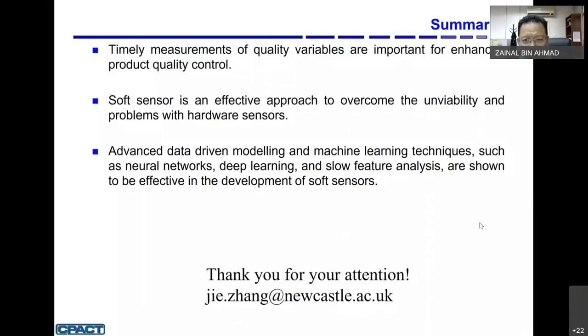Right. Okay. So the selection. Actually here you can see we show this plot of eigenvalue. It's quite similar to PCA. You show how much data variation is represented by each principal component. Correct. So here we try to find this turning point. At that turning point, it indicates that if you select more slow features, you are taking a lot of noise into the data. So actually we stop at the turning point.